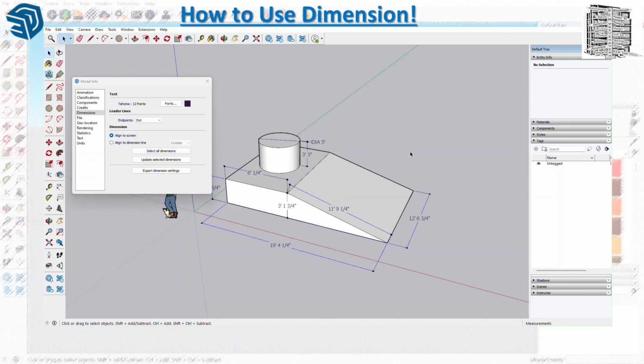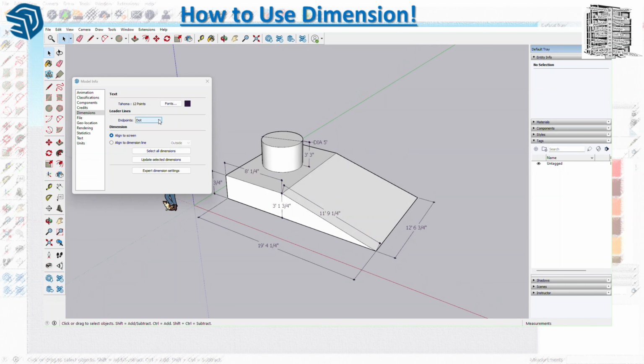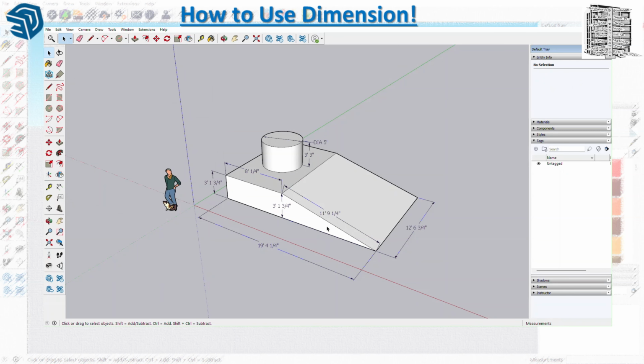You cannot get an angular dimension in SketchUp. It only gives you a measurement between 2 points. If you want to get that kind of dimension, you need to install a plugin or any extension from the Extension Manager.